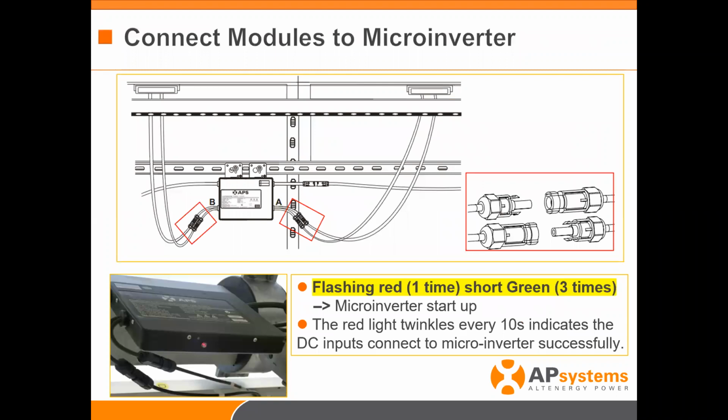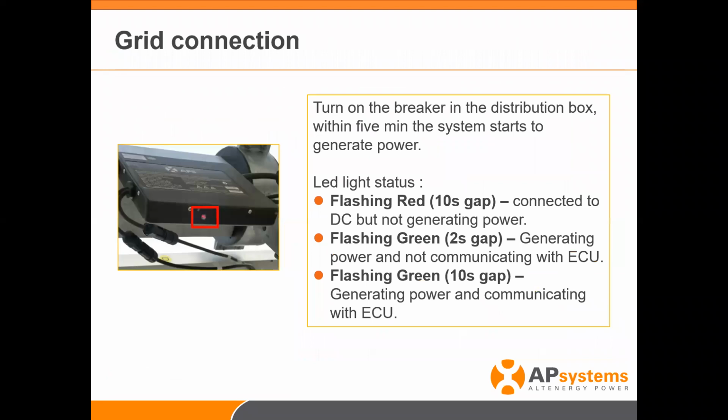Microinverter connections, I talked about this before. When you make that first connection, that DC connection here, you're going to get a flashing red and 3 flashing greens, telling you that the microinverter has started up communication, not power production. There's also all kinds of information that can be gathered from this LED. And again, this is standard on all of our products, even our legacy products. That LED has been on this product since the beginning of time. The LED status lights haven't changed. The configuration is exactly the same. So like I said, once you know one, you know them all.